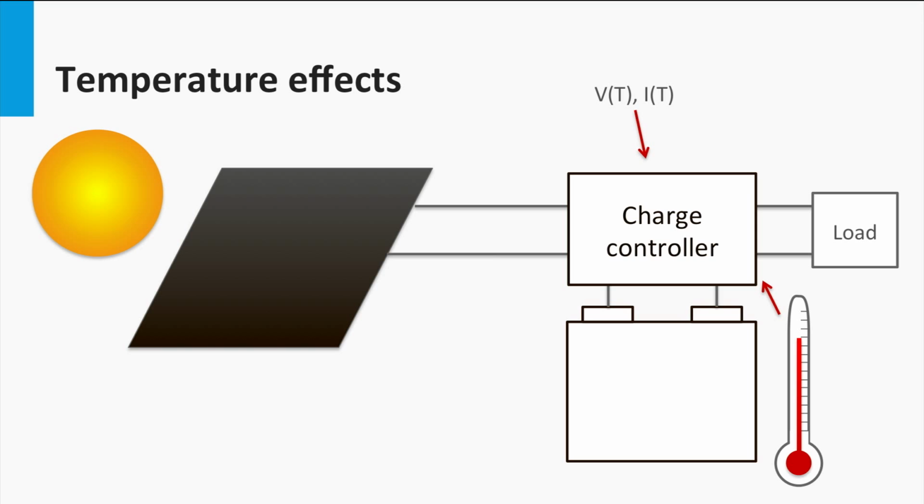Therefore, it compensates for temperature fluctuations and dynamically decides how the electrical specifications like operating voltage change with temperature. It successfully keeps the battery operating in the desired range of voltages depending on the temperature. For this reason, the charge controller is usually kept in close proximity to the battery, so that the battery's operating temperature is close to that of the charge controller.